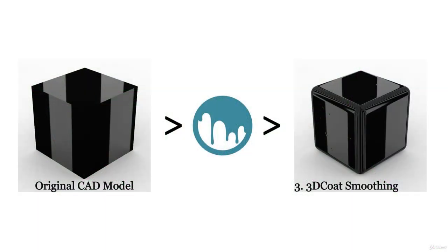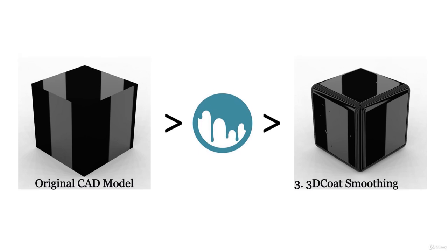I'm not going to go into detail how to make good meshes, but it does involve having properly made NURBS surfaces, and also if you can, you should tend to have quads in your mesh. And if possible, you need to have those quads oriented in a proper way.